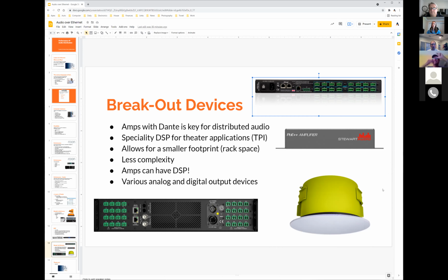There are a lot of surround processors on the market, like the Lindorf MP60 that supports AES67, or the Dolby Professional product like the Dolby CP850 that supports AES output that can go into this, speak Dante, move digital audio properly into the box at 48K, and then all the DSP for the theater is done in one box. That is a brilliant architecture. It keeps the DSP out of the amps for the theater, which is a very good thing. It really ups the performance for these reference cinemas.